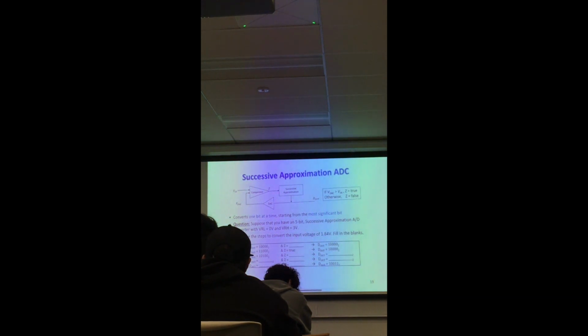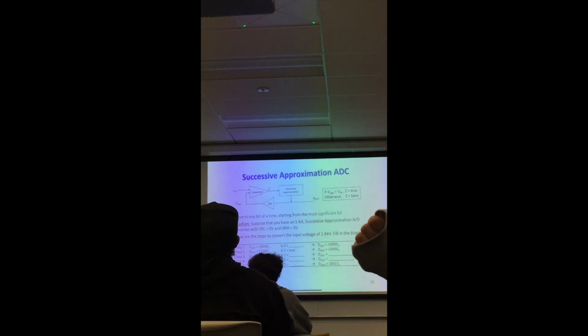And tell me again, why is this type of analog to digital converter used in the majority of microcontrollers? Give me one reason. It's the fastest. The fastest would be the flash, yeah, with resistors. There's nothing that can beat it. So it's not the fastest, but there is some reason why it is actually used in this way, and we have to understand it.